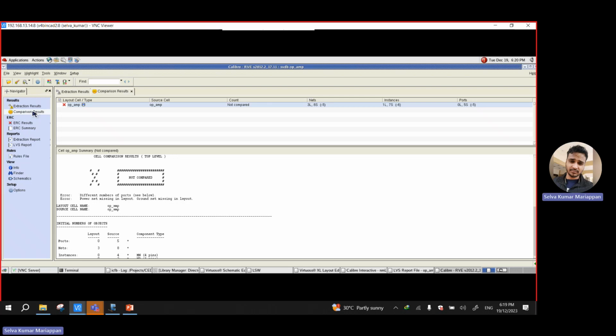Okay, that one you need to go to your file. Press your file browser. Go into your library. Remove, open. Which file is that one? Open. Go to schematic. So you see this lock file, right? This is locked. It's already locked, so you delete that one. Okay. Now try again. Your schematic, reopen. Can reopen, can refresh. Try reopen. Oh, nice. Yeah. Thank you.